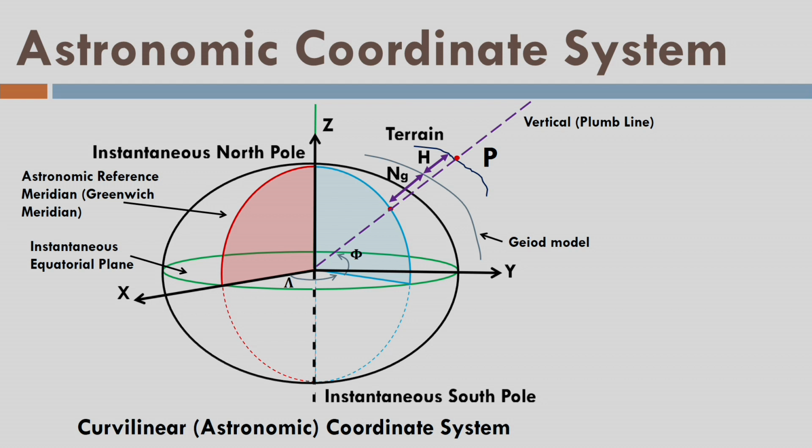They used to determine some two-dimensional points. They used to determine the vertical heights, and these vertical heights are the orthometric heights, capital H. Using this one-dimensional survey for vertical and two-dimensional survey by triangulation for planimetric, they used to combine this data and fit an ellipsoid through those 3D points, and that was the idea.